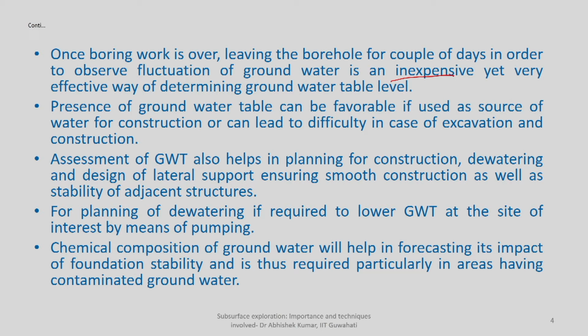The presence of groundwater table can be favorable if it is used as a resource for construction purpose. So, if the groundwater table is shallow, you need not bring water from the surrounding area or any other resource for construction and for different stages, rather it can be used as a source.